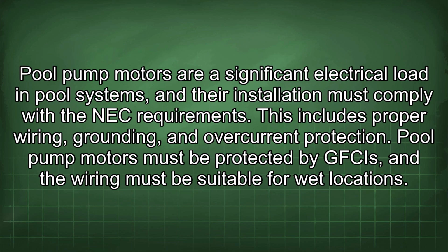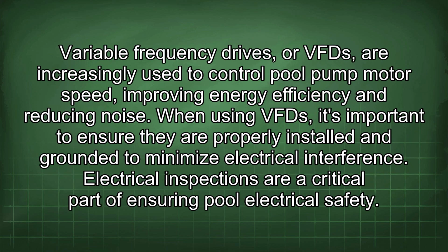Pool pump motors are a significant electrical load in pool systems, and their installation must comply with the NEC requirements. This includes proper wiring, grounding, and overcurrent protection. Pool pump motors must be protected by GFCIs, and the wiring must be suitable for wet locations. Variable frequency drives, or VFDs, are increasingly used to control pool pump motor speed, improving energy efficiency and reducing noise. When using VFDs, it's important to ensure they are properly installed and grounded to minimize electrical interference.